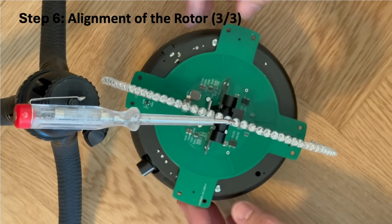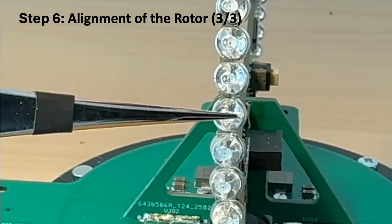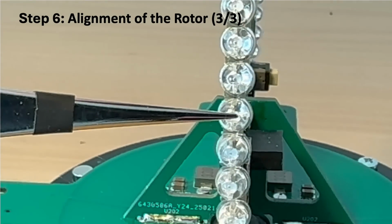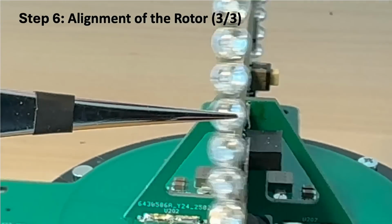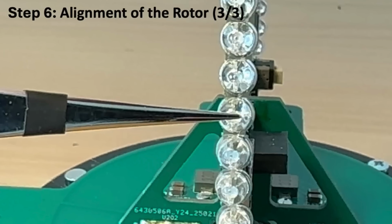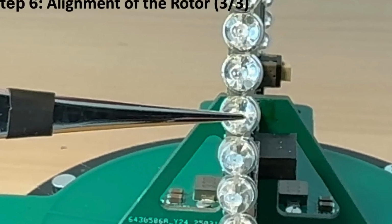The final step is adjusting the beta angle. Here as well, a pointer is mounted in front of the display using a stand. By comparing the LED board's position at 0 degrees and at 180 degrees, you can check if the alignment is correct. Keep in mind that due to the interlacing, there is a shift of half an LED width. So at 0 degrees, the pointer should hit the center of a specific LED, while at 180 degrees, it should point exactly between the two LEDs.